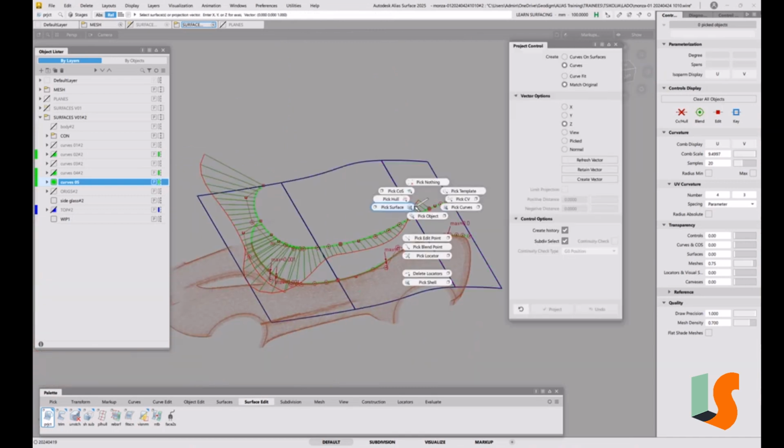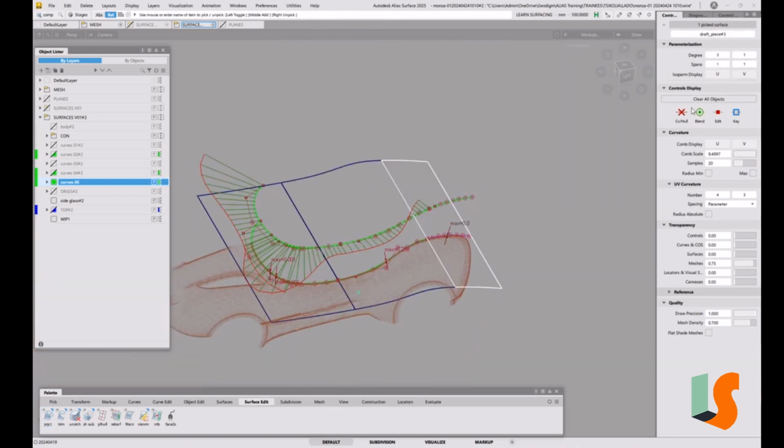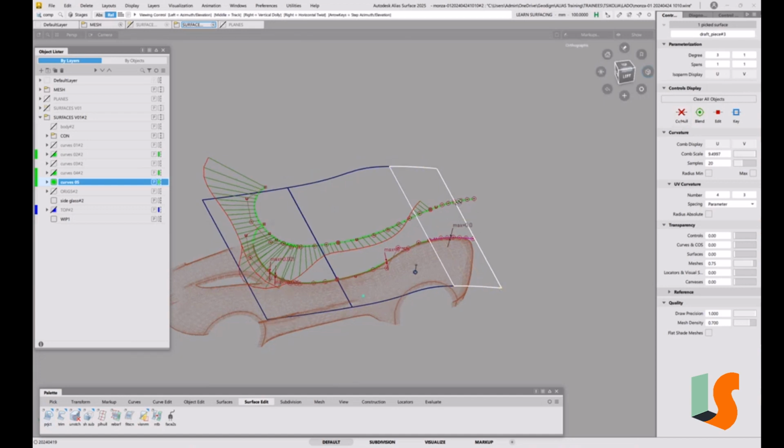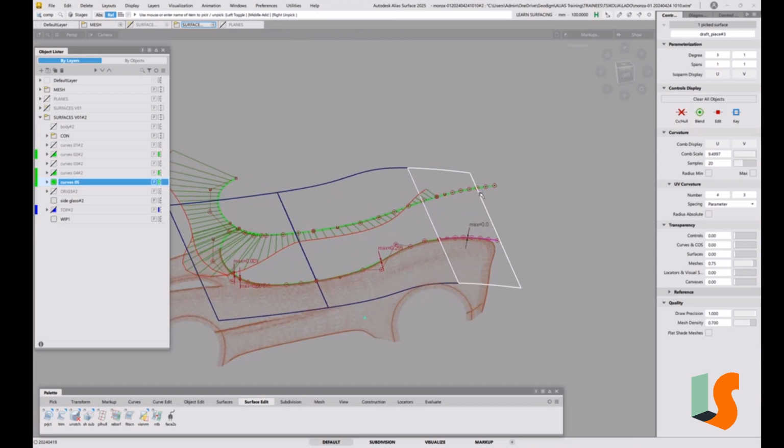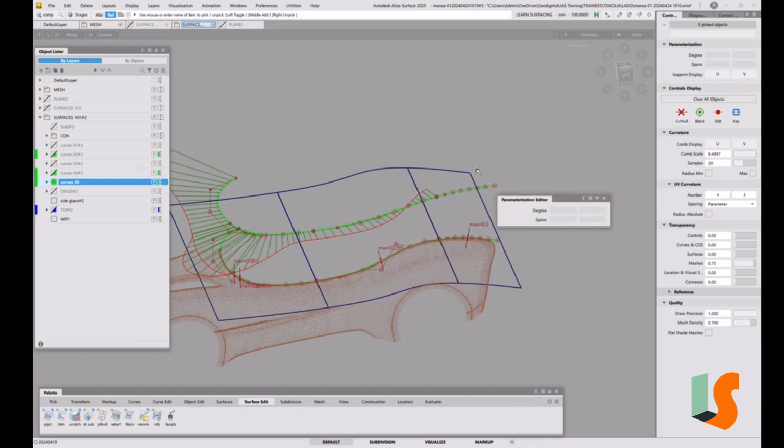And that's because we've got a fairly simple surface there. It's only degree 3, so combining that with a high degree curve there, which could probably be lower, to be honest. Let's just try that. Let's see if we change the degree down a bit of that.